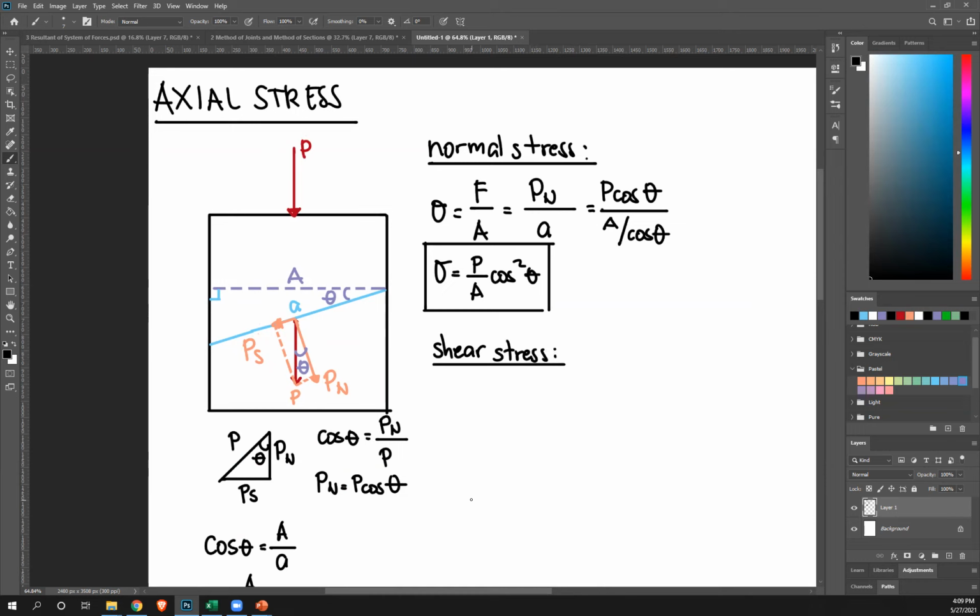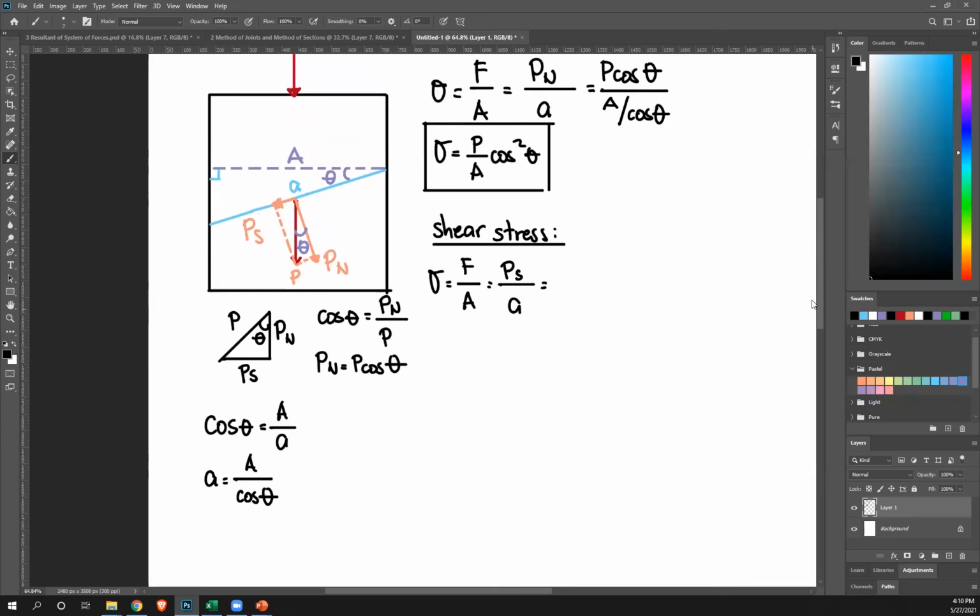Same thing. Our equation now is V over A. Recall from your physics, right? Shear force. If you discussed it in your physics, it's just force, parallel force over area. We can use it as V over A, V being the parallel force. Or if not, you can first use the general equation F over A, then get more specific. That's actually PS over inclined area A. Okay, now let's get the equation for PS.